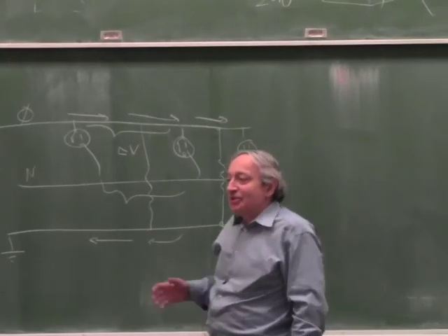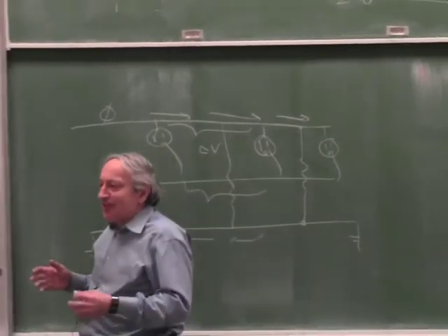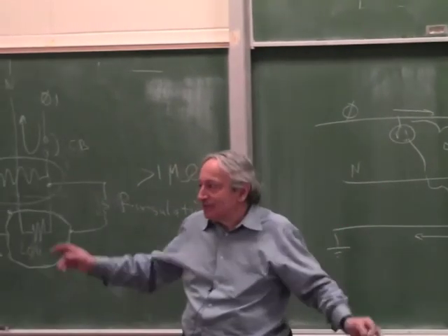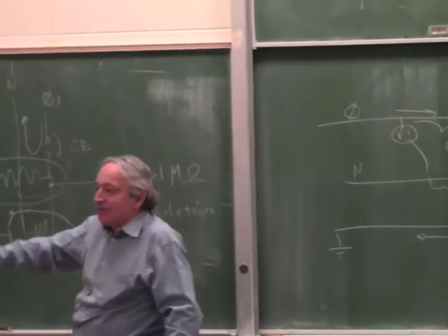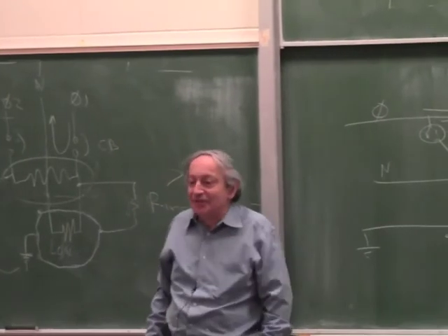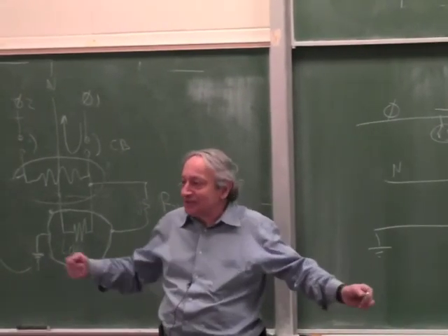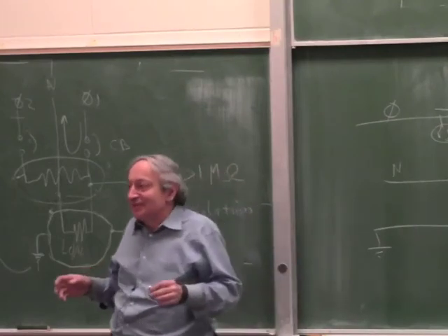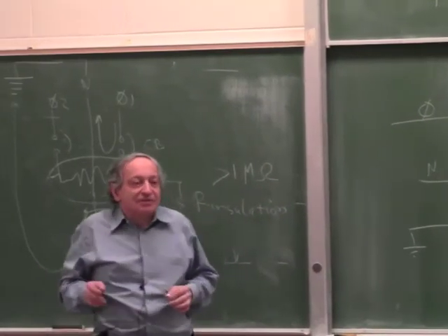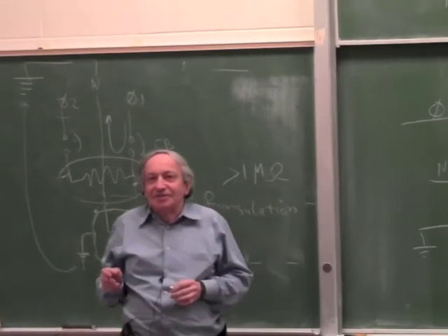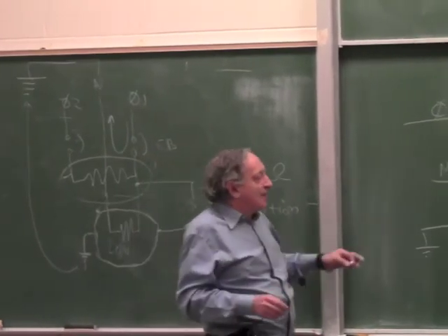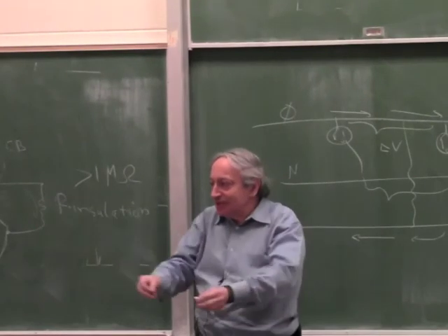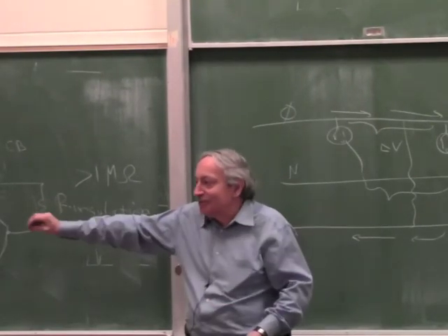So that means when you ground things, you have to be a bit careful, because you may have a sensor and a computer at two ends of the room. The sensor is grounded to this outlet, the computer is grounded to that outlet. You can actually have some currents through the ground. So ground is not truly 0 volt. And that is the reason why in very sensitive systems, sometimes you don't want to ground different parts to different grounds. You want to bring all the grounds together and then take one wire to ground.